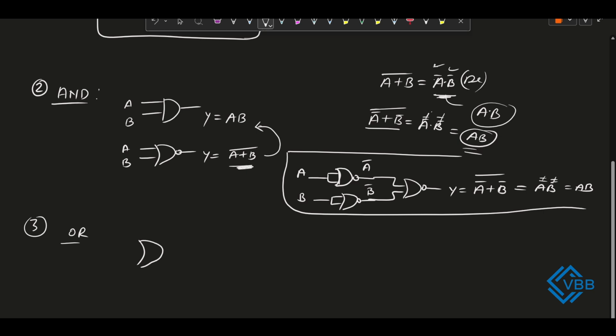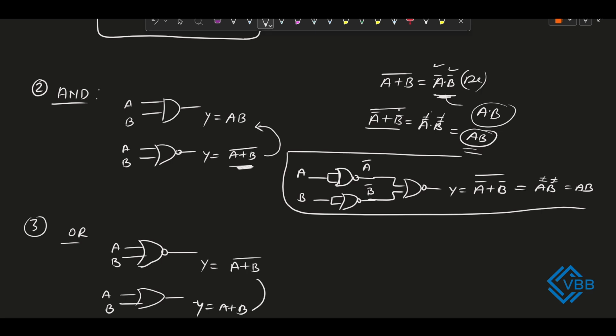So just if we will complement the NOR gate output, sorry, then we will get the OR gate, means this is the expression or output of NOR gate A plus B whole bar, and this is the output expression of OR gate A plus B. Okay. So anyway, if we are able to complement this final output, then we will get this OR gate output.